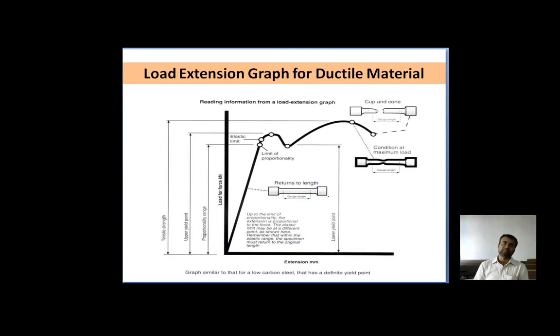So this particular area of the material is showing the elastic region, the limit of proportionality, that is Hooke's law: stress is directly proportional to strain. From the stress-strain curve, to the elongation of the material, to the yielding stress and strain, that is how the material behaves when we apply the load, and the graph shows the constraint of that deformation or elongation of the material.